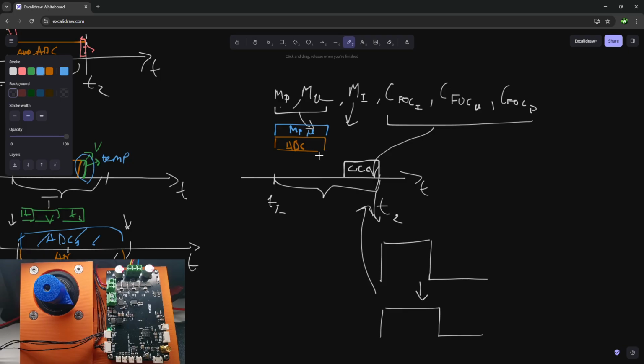Given that in our current design it is an SPI component, we can communicate with it mostly using direct memory access, or DMA, which is a mechanism that allows us to send data automatically. You just set it up: I would like to send this message and read this answer, and tell the MCU, go do it, and I will check the results when they are ready. So this is how it works.